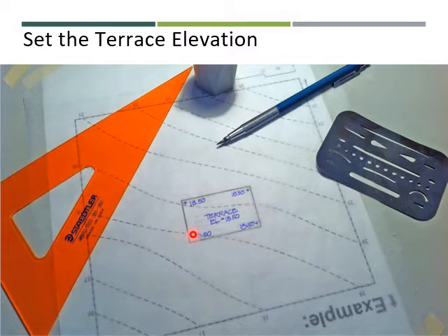So each of these corners are representing the inside of a terrace. This is a terrace, this is not a building. So remember, as we go through the course, do not set the elevations for the corner outside the building on the building itself. This is a terrace, this is probably a paved surface. These are the spot elevations and how you would represent them both on paper and in AutoCAD. And this represents a completely flat pavement surface. So we can imagine this is some sort of pavement that allows water to flow through and not simply flow.